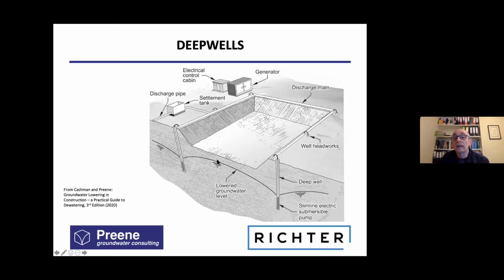And this is very effective for deeper excavations. I've worked on jobs where I've been sinking shafts 50 or 60 meters deep, and we've installed a single stage of well points, and they've been able to cause very significant lowering. And in the mining industry, for example, wells like this are sometimes used for excavations that are hundreds of meters deep.